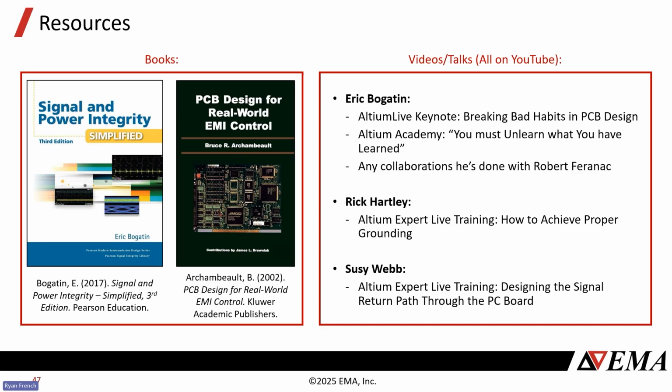Yeah, so in the ESD section where I broke up the chassis and digital, and I said keeping the ESD energy on that chassis is important. I know there's probably at least one attendee here today who I just did the PCB design rule training with, who is probably thinking, Ryan, you just told us something different. And this is where signal integrity, EMI, and other effects kind of butt heads a little bit.